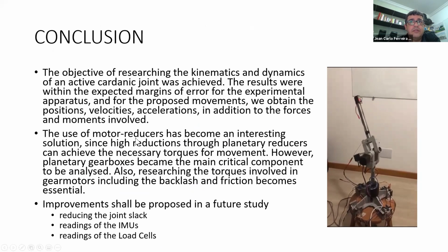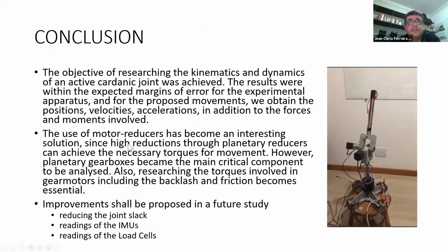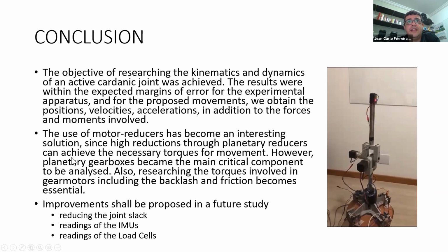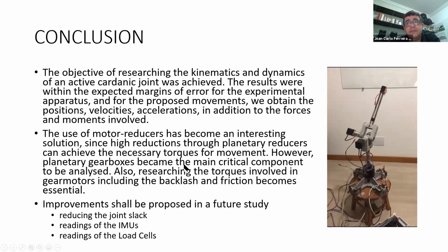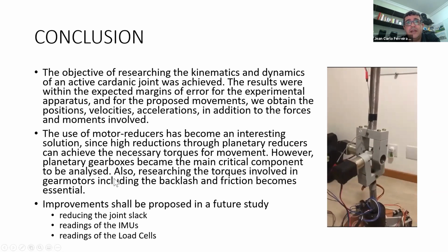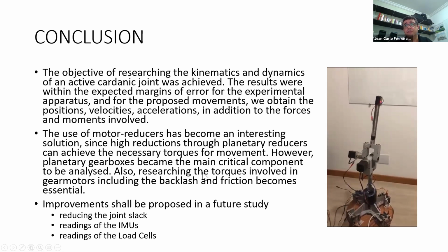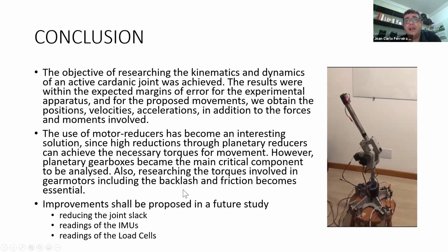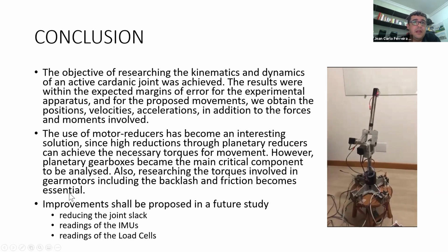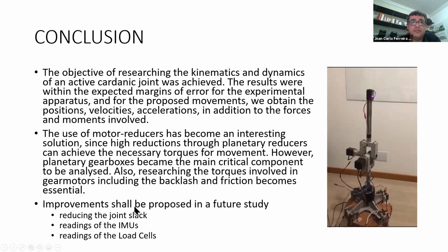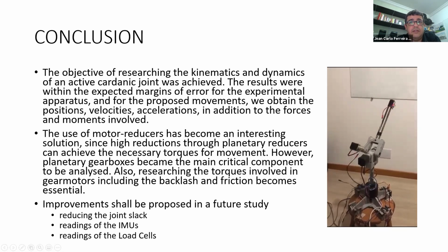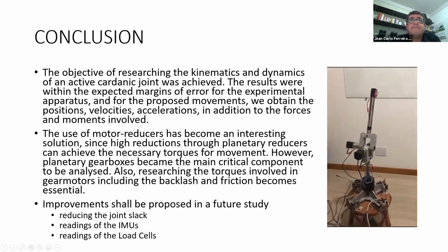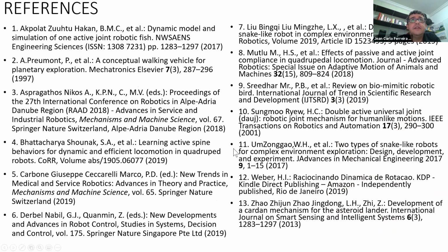The use of the motor reducer has become an interesting solution, since a high reduction through a planetary reducer can achieve the necessary torque for the movement. However, the planetary gearbox becomes the main critical component to be analyzed. Also, researching the torques involved in gear motors, including backlash and friction, becomes essential. Some improvements should be proposed in the future, for example, reducing the joint slack and improving the readings of the IMU and load cells. This is my reference, and that's it. Thank you for your attention.